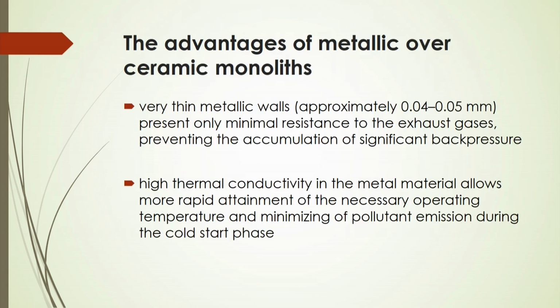Whereas, there are also advantages of metallic over ceramic monoliths, because two types of monolithic reactors have been developed: one is ceramic monoliths, another is metallic monoliths. In the case of metallic walls, very thin metallic walls, approximately 0.04 to 0.05 millimeter, present only minimum resistance to the exhaust gases, which may prevent the accumulation of significant back pressure.